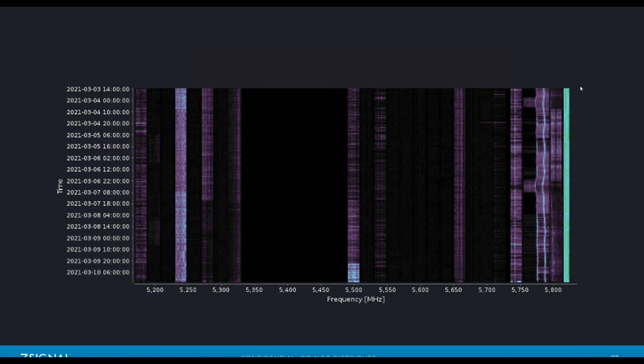It looks pretty small, looks pretty harmless. Just that tiny little wiggle worm there on 153, but 100% duty cycle, loud enough that any Wi-Fi station on that channel will hear it and never transmit. So never use it. Exactly. And there you have it.